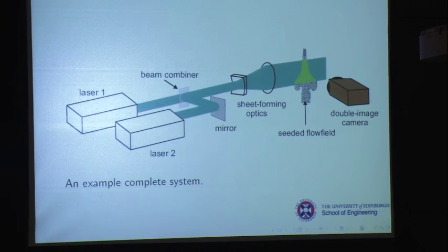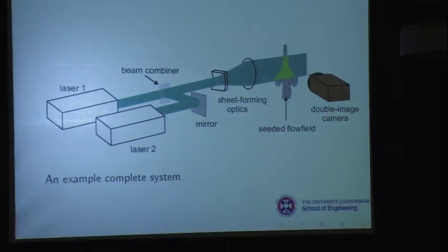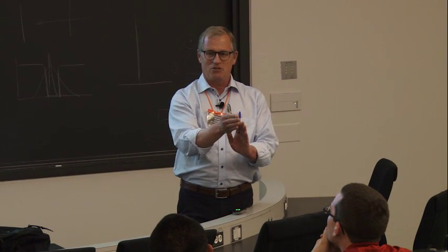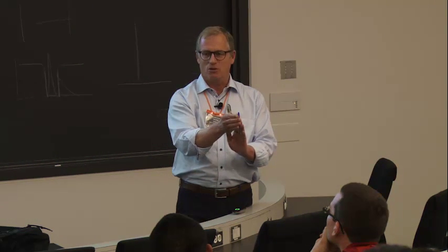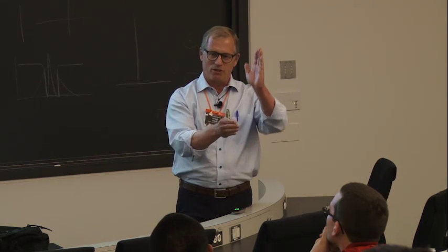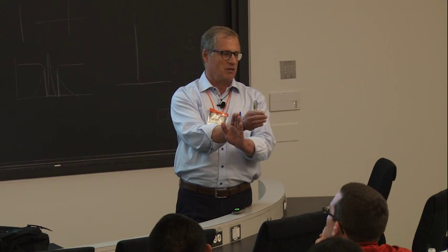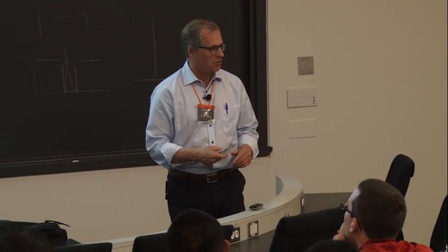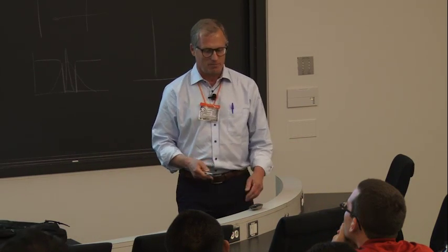So now you just have to shift charge and dump the first image behind that vertical register, each vertical register. So in 1 microsecond, you can dump the first image into that vertical register, and then the second one is just going to have to be open, and that depends on how you shutter the camera. It's open for a long time. But you read out the first register, then you dump the second image into the register and read that out. So you can separate the two images by as little as a microsecond now.